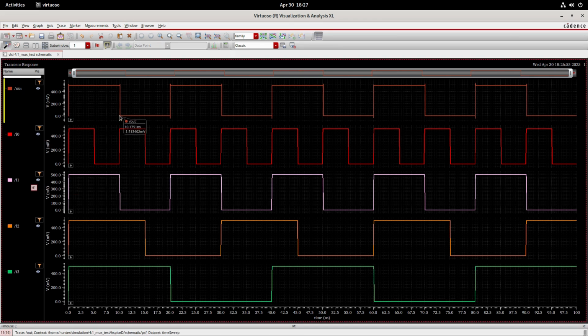As I told you previously, we need to give the inputs on even and odd numbered pins. If you give the inputs like I1, I2, I3, I4, then you will get a wrong output. You see, this is the reason I give the input pins like even and odd numbers. Now I think you can understand this.